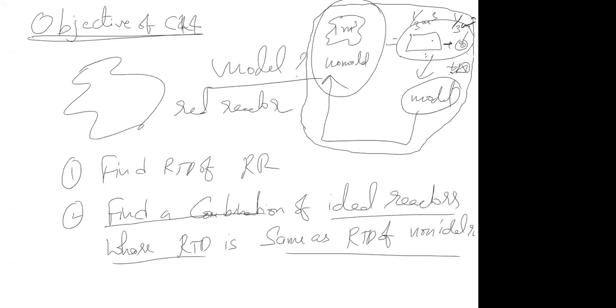Yes. Now somebody's question I will read: non-idealities can also mean that in a CSTR there is no... Yes, yes. Non-ideality means anything which is not behaving like an ideal PFR or ideal CSTR. Let's take a first order reaction. What is my objective? I should have an ideal PFR. If somebody gives me an ideal PFR, then that is what we are studying.